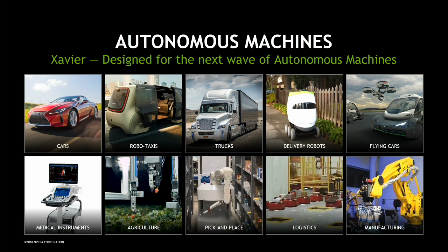And so we looked at what we need in an autonomous machine chip. With DL, we need tens of deep learning teraops. And then we looked at compute. Again, people are doing different things in computer vision, as we just heard. In some of these high-end systems, you want tens of tops of computer vision compute performance. So we started to look at how we can build a chip that can fit in these markets, but still be efficient and meet the power targets that some of these may have. And so we knew we needed to design some new things.